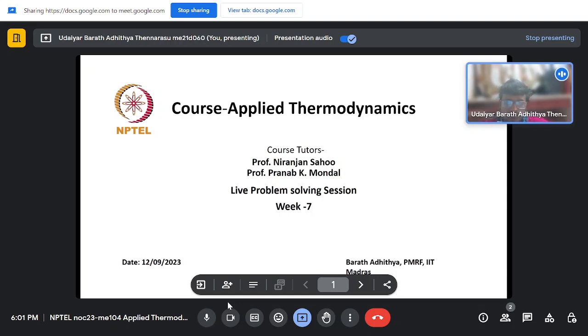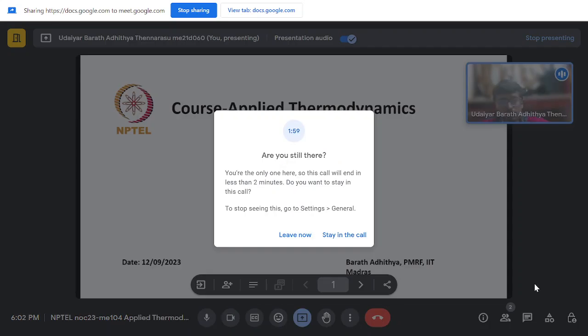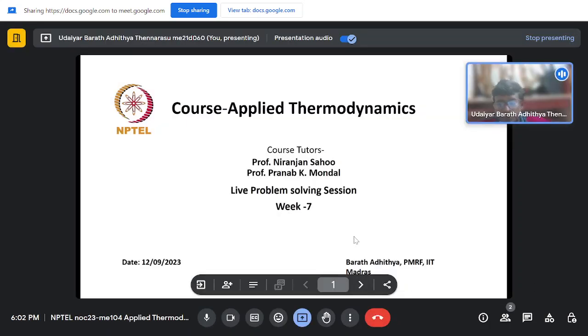And also previously we saw knocking. In the process of combustion, the flame should go out near the walls, it should not go out in between, otherwise there will be incomplete combustion. And we'll see some numericals on the flame, how to calculate those: at what velocity the flame is traveling, how much time it takes, at what angle the flame is initiated, numericals related to that. And also we'll see exergy analysis of an internal combustion engine.